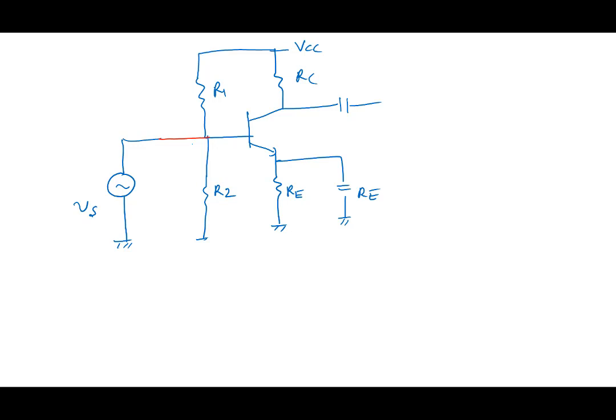Previously, we needed a higher voltage, let's say 1.7. So in this case, what would happen? Suppose somebody did that. What do you think will happen to the amplifier? Somebody says, anyway, you're saying the capacitor is acting like a short, so let me remove it and connect it directly. What would happen to the biasing? How would you calculate the bias point? What do you do to the source?